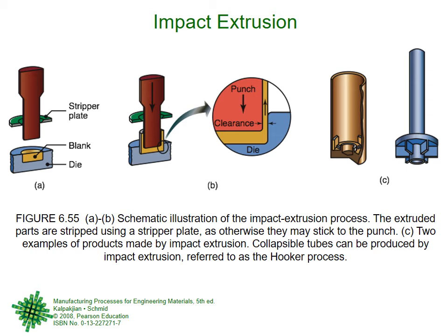But remember the impact test: you are dropping the hammer in the impact machine, so all the load is applied suddenly and it breaks. So in both the tensile test and the impact test, you are fracturing the specimen. But in one case, you are gradually increasing the load, and in the other, you are suddenly applying the load.